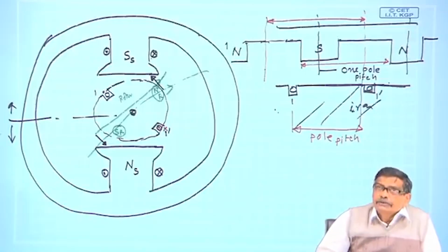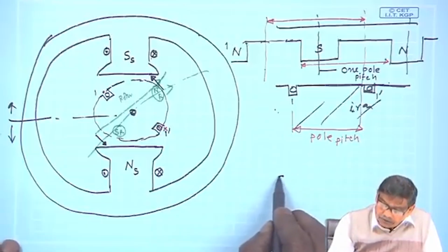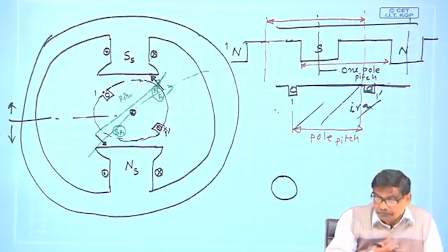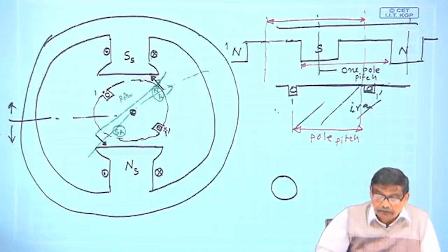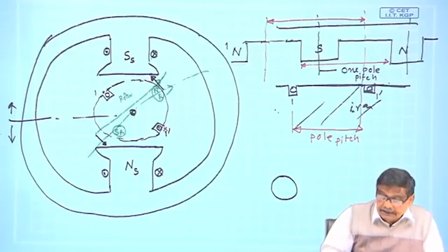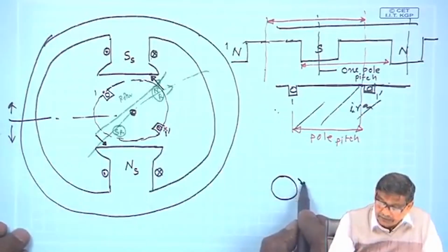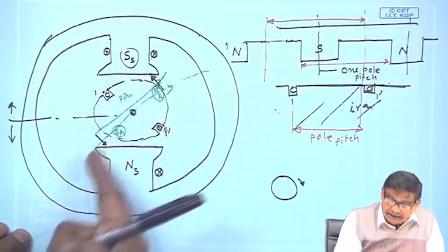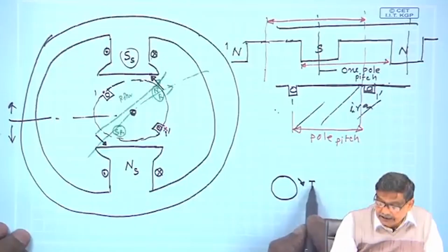But eventually you will observe, it is just an observation, it is running at a constant speed, and therefore, suppose this is the rotor of that motor, I do not know in detail what is inside that motor, but with this argument I can say several things, that NR, SR has been produced, NS, SS has been produced, and it is running at a constant speed, and the interaction of this SS, NS and NR, SR gives you electromagnetic torque.